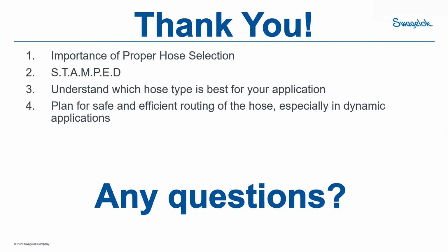Are PTFE hoses appropriate for vacuum applications? Yes, they are. However, not to the same vacuum level. We say that a PTFE core hose is rated to 28.5 inches of mercury, if you use those units, but it's about a 95% vacuum. A metal core hose is rated to 99.9999% vacuum, about 0.001 millitorr, I believe. So they're different vacuum ratings, and it's important to keep that in mind when selecting a hose for vacuum.